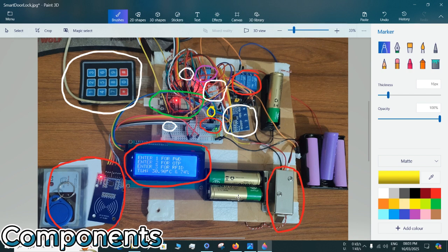And most of the components over here are 5 volt or 3.3 volt tolerant. For example, the GSM module and the RFID module are not 5 volt tolerant, so I had to power them up separately. But most of the other elements are 5 volt tolerant. For example, the display, the relay module, the DHT11 temperature plus humidity sensor module, all these are 5 volt tolerant. But these two batteries, the pair of lithium-ion batteries that I've used here, generate more than 8 volts when they're completely charged. But my appliances are not 8 volt tolerant, rather they are 5 volt tolerant.